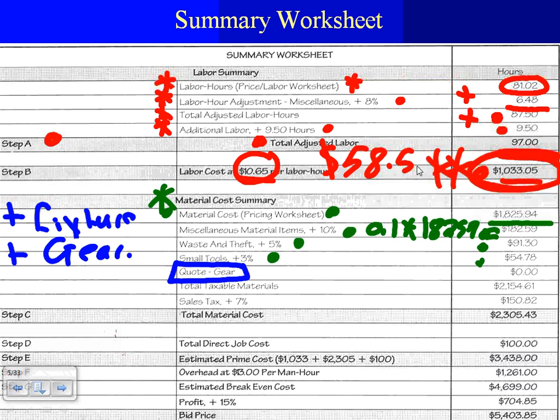Because when you take a fixture in estimating software, they have 2 components you have to control. One is the price of the component. No problem, I can make it any price I want or follow the schedule. Usually I put 0 for fixtures. Why 0 price? Because I'm going to quote them and leave the labor. So this fixture will be taken in the software. It will be assigned labor hours, but it will be assigned $0 for a price. Why $0? Because I'm going to add them at the end as a lump sum. So yes, we have to take them in the software and assign the labor to install them, but dollars for pricing them, $0. Why? Because they're going to be quoted at the end.